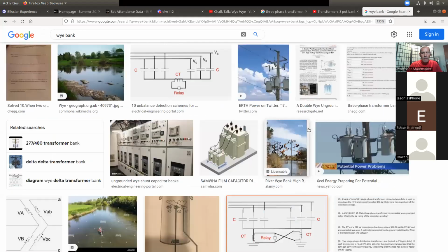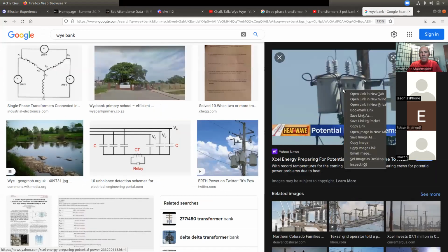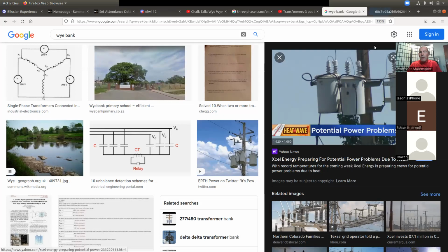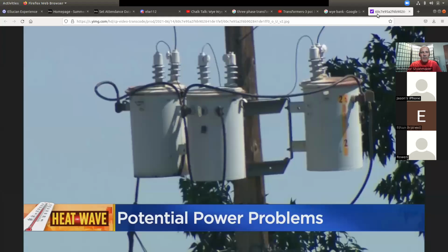Yeah, but you're only using two lugs on the Y. Open image in new tab. So check this out. The center transformer is the dead giveaway for closed delta and Y. If that center transformer is not a lighting transformer, a transformer that will not power my house, this is a Y bank. Do they have a neutral in the center? No. Then this is a Y bank.